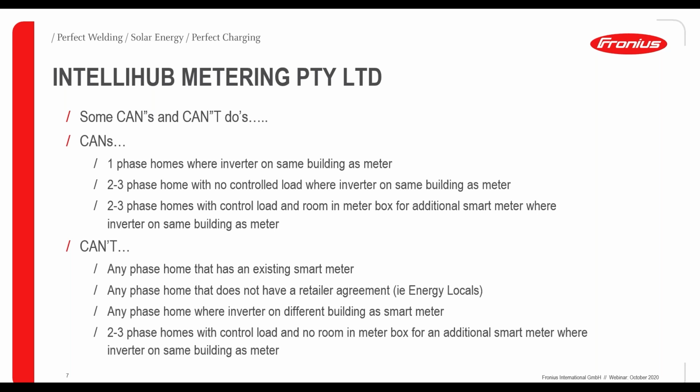Some things you need to watch out for: any phase home, so single, 2 phase or 3 phase, that has an existing smart meter. If it's already got a smart meter there, the retailer is not going to be swapping it out for an Intellihub one, so you need to be wary of that. Also, anyone that doesn't have a retail agreement with Intellihub, for example Energy Locals don't have one.